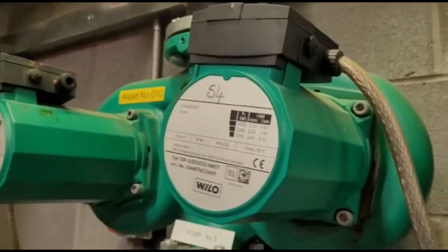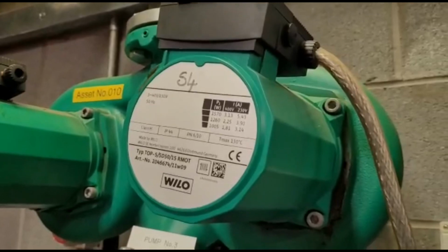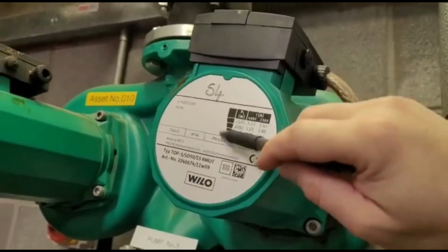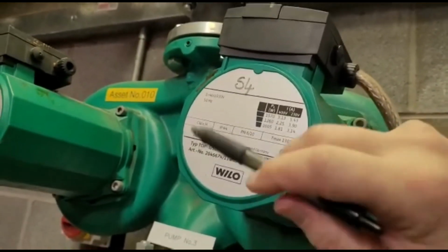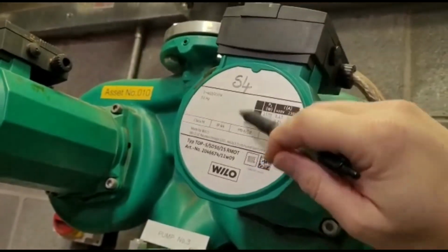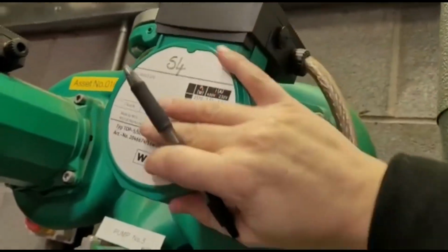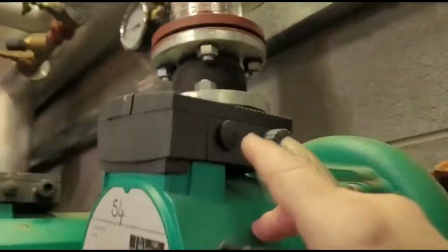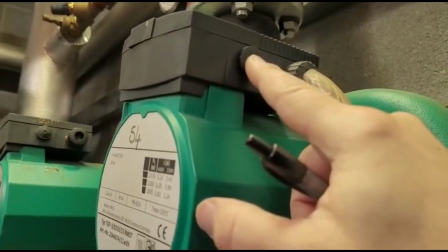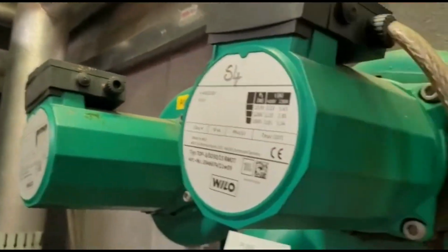Right, I've just come round to the CT pumps because they're easiest to get to while I was around there. Sometimes these will trip, but you might think they're knackered, but they're not. I have a magnetic swirly thing and it works on magnetism. It tells you if they're running or not, but that's only telling you if it's magnetised or not. It doesn't actually tell you if it's going round or not. But if you come to it and it has tripped, if you look at the side at the control box here, a lot of people think they're knackered but they're not. There's a thermal overload switch there, and it might have tripped, so you just press it in, resets the pump, and away you go again. Cool.